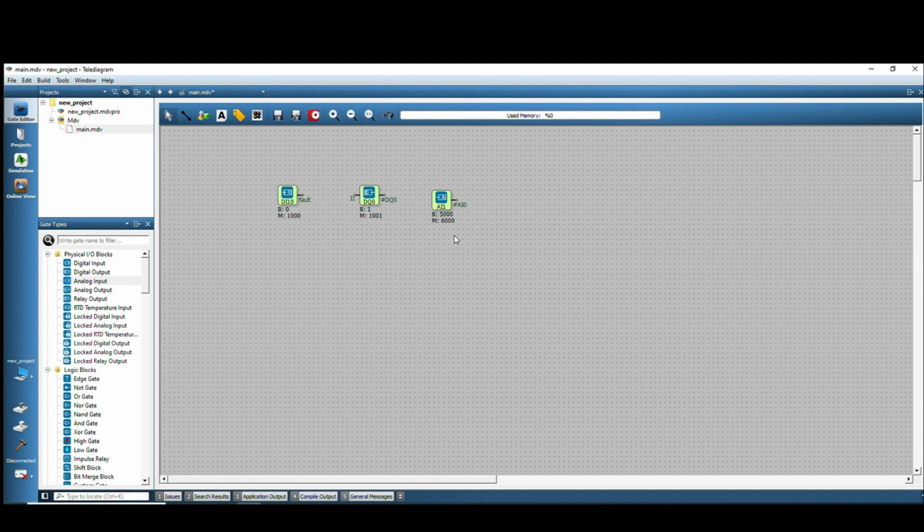Analog blocks, which are float values, start from 6000 and continue with an increment of 2. You can increment like 6002, 6004, 6006 for the binary values. Word registers start from address 4000, and long registers will start from 8000.